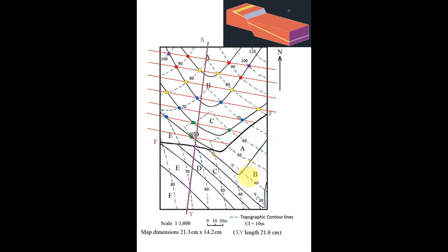After this, let us move to the lower rock side, and we have again this AB junction, and on this AB junction we have the 50 contour. I'll just pass a line through it, and now I'm using blue color strike lines. The interesting property here, as I already told you, is that these strike lines are going to be at the same distance, the reason being that the inclination of the rock is not changing because of the fault, right? Hence the strike lines are going to be at the same distance. After 50 we have this 40 which is there. I'll pass a strike line.